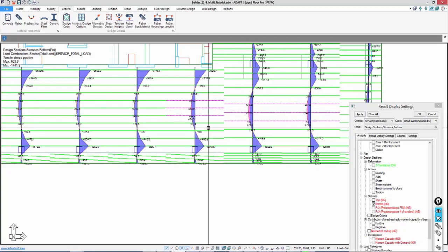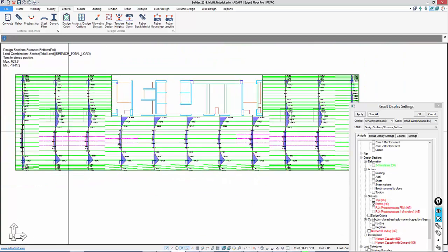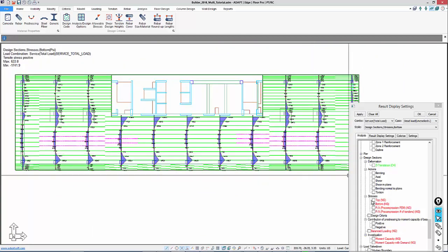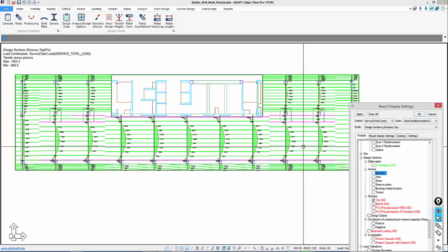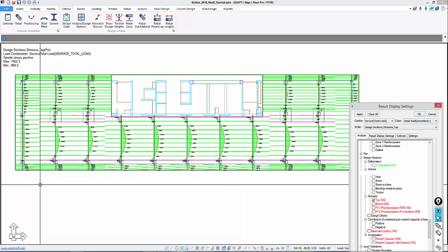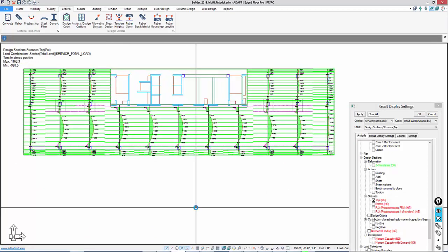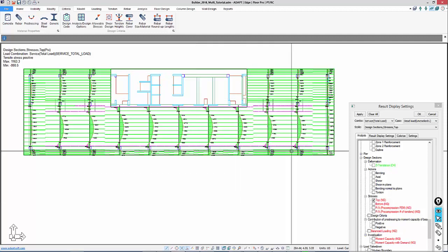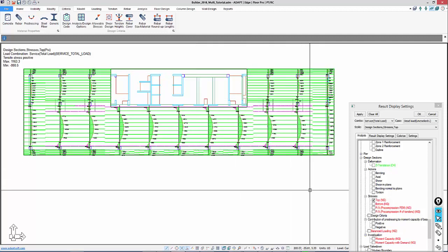And so we have a bottom failure in flexure here in tension, for stress, and then at the top we have some overstress here near the supports at the top, especially along this edge here and along the bottom shown here. Okay, and so we're going to, in the next segment, use the optimizer to show how to optimize these cables in a couple of these locations for producing a result that meets the allowable stress.